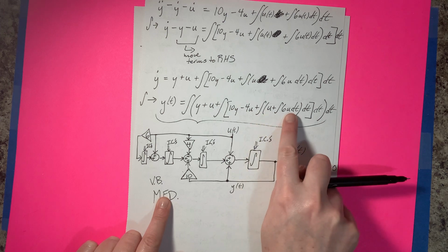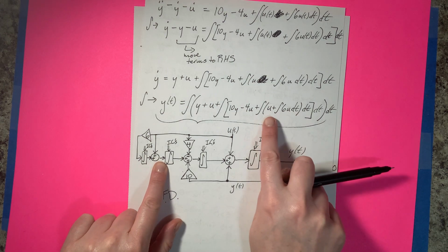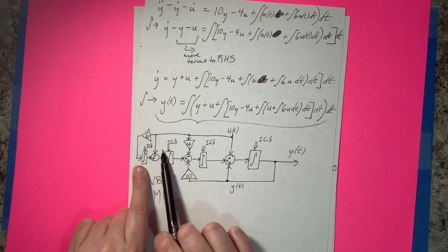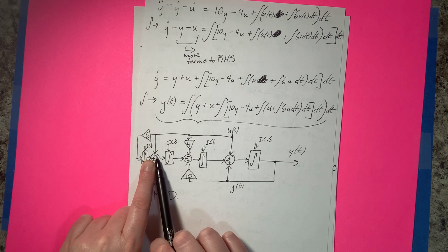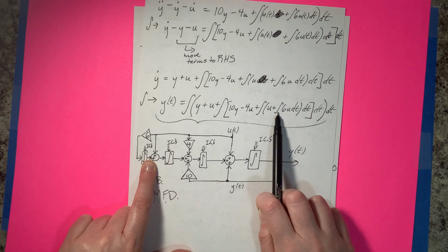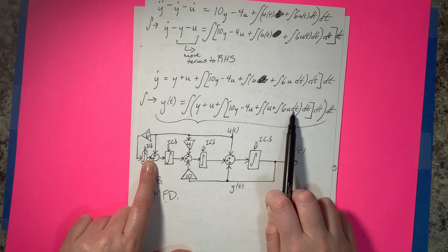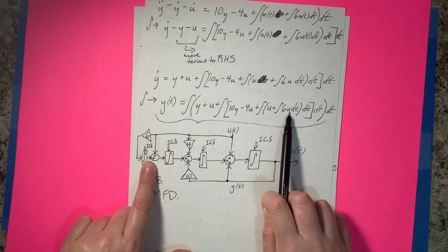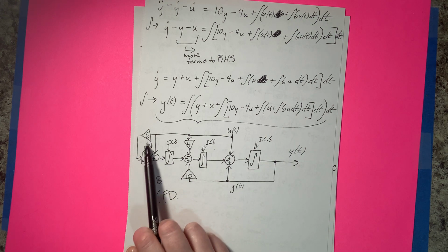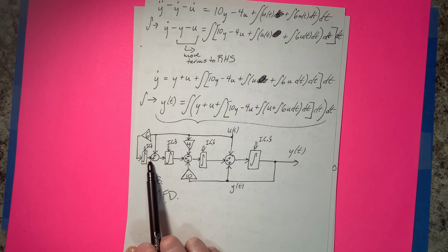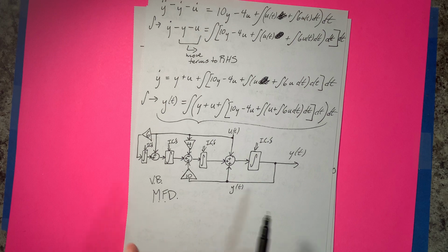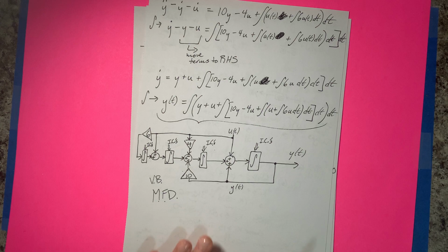Okay, so we now have 2 elements that we need to go into this integrator. We have the u, which I put at the very top of this diagram, so I just pulled it down here with this common line and added it into the summation block. And then we have the integral of the 6u. So actually we have a u here, and we have an integral of some gain times u. So our gain happens here, and then I opted to put the integrator right here and add it into the summation right there. I thought that kind of gave it a clean look. Sometimes it works out very neatly like that. And so that's our completed math flow diagram.